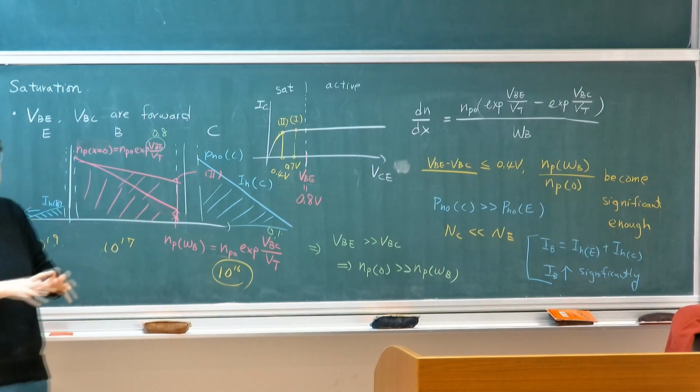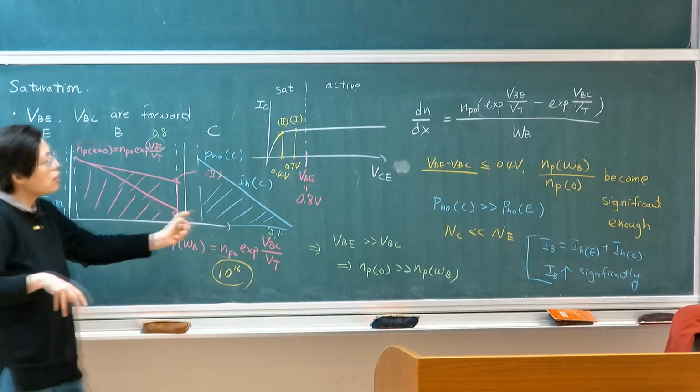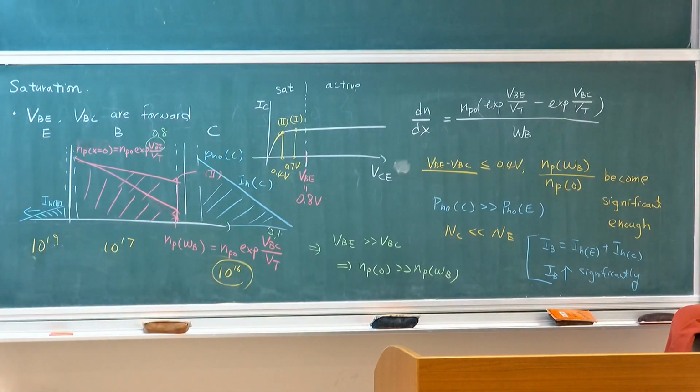The other thing is that you would then have a significant raise of base current because you're forward biasing both junctions. So you need to supply both. And this will be much more significant because the emitter current has been deliberately suppressed, because I heavily doped this. This is deliberately done. But this is a side effect we can avoid.